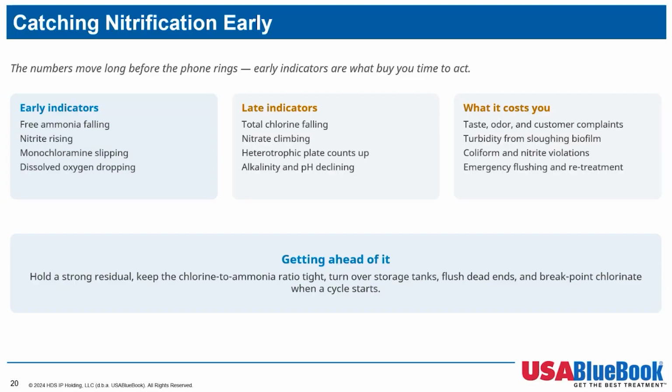By the time total chlorine is falling and plate counts are up, you're not managing anymore, you're responding, flushing, retreating, and explaining. So the distinction I'd like to take from this slide isn't early versus late indicators. It's whether you find out from your data or from your customers.